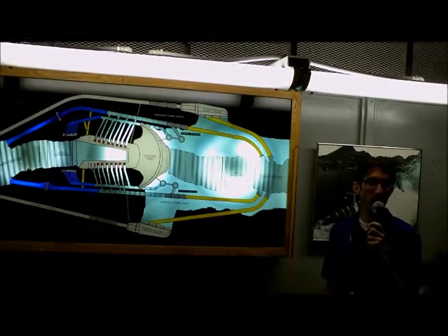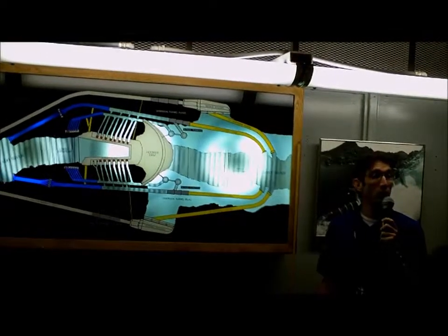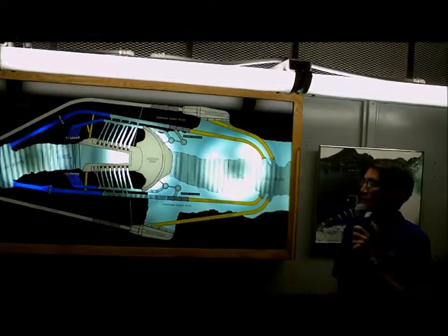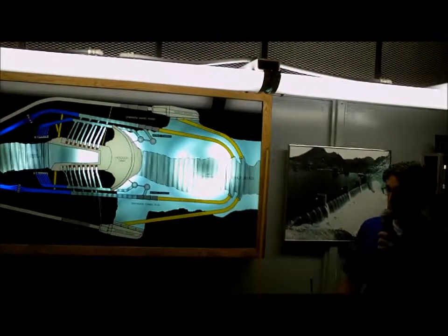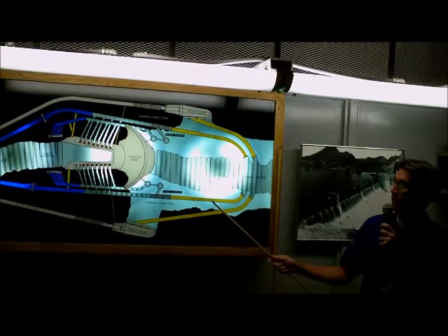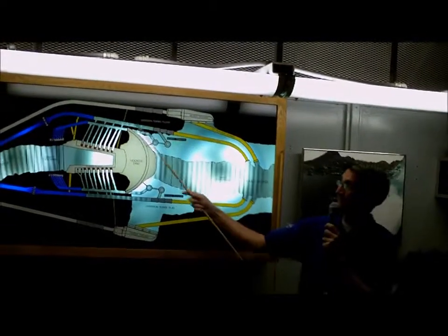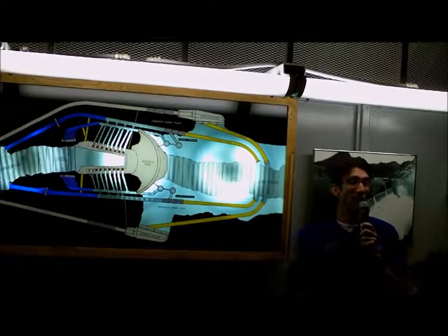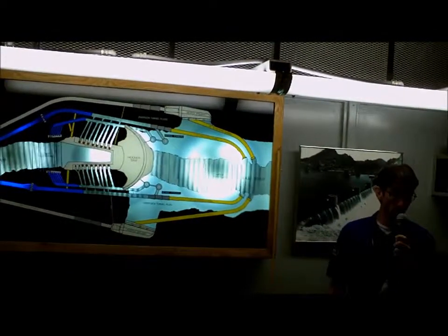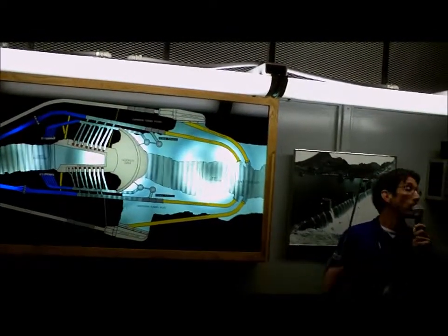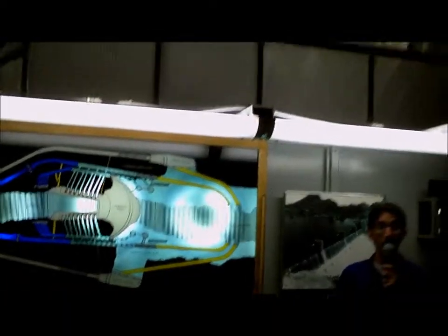And one of the first tasks that the workers needed to overcome was to divert the Colorado River. This was accomplished by building 4 diversion tunnels, 2 here on the Arizona side and 2 on the Nevada side, each of which is about 4,000 feet in length and 50 feet in diameter, once lined with 3 feet of concrete. If you look up, you can see that original concrete right now. So we are in one of the diversion tunnels.